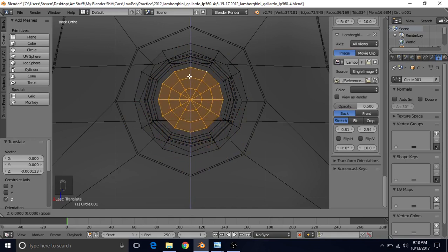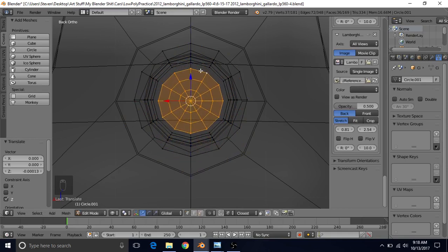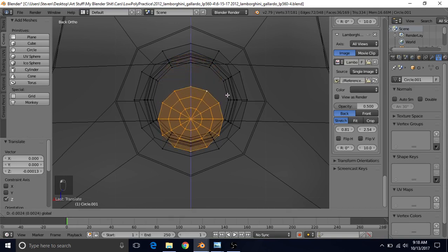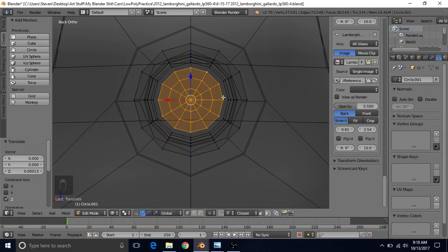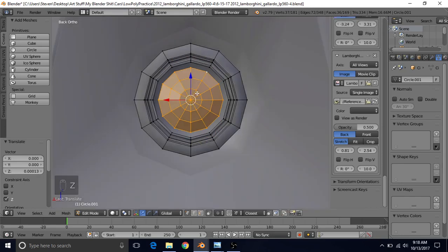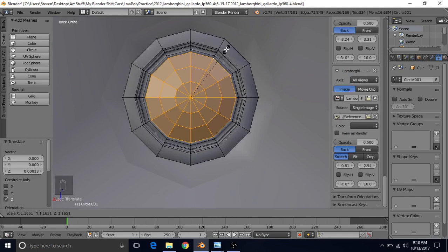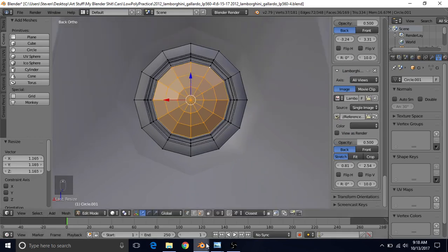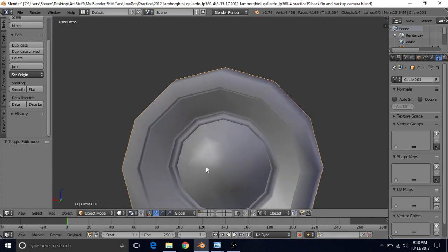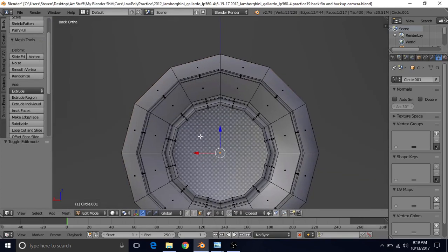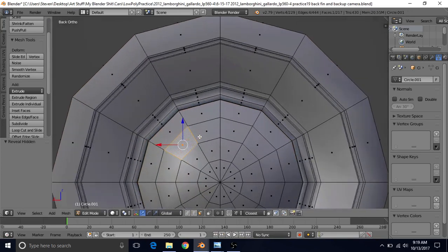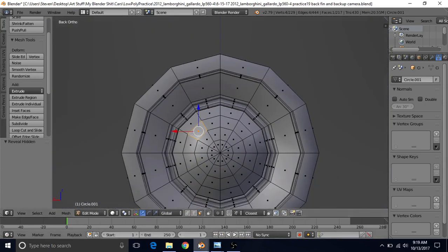And once you have it basically in position, like this, since these two vertices are close to each other, and this one is the center vertex on the horizontal center, you can now grab on the Z and hold Control to snap here so that they're perfectly lined up like that, and then you can just scale it to be whatever size you need. So if you want it to be this big, you can scale it to be that big. I think I may have gone with a bit smaller. Well, nope, actually I went just about the same size as what I have.